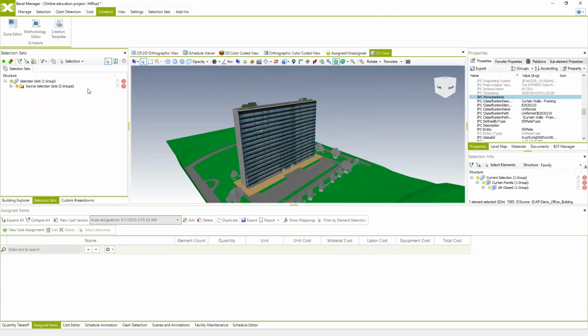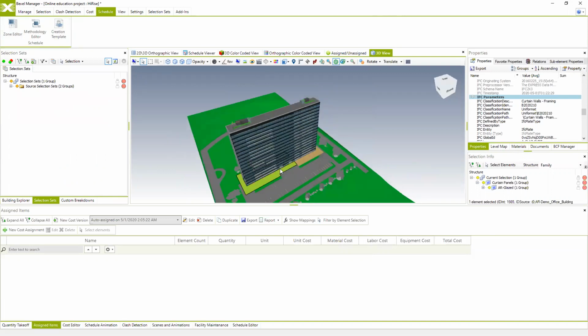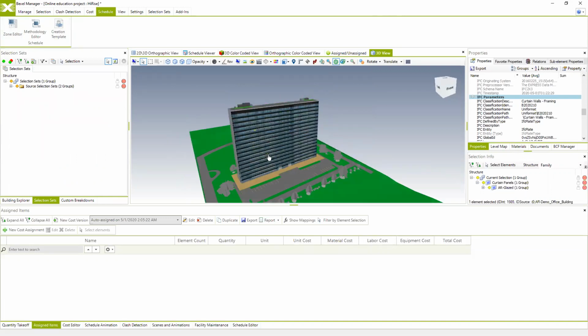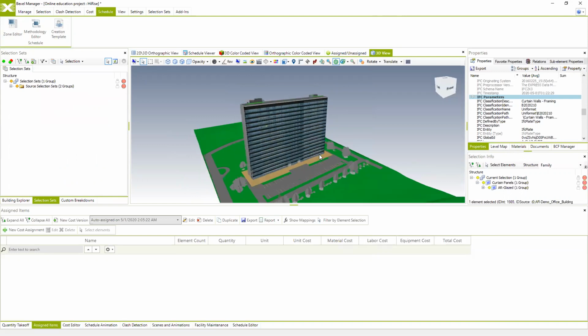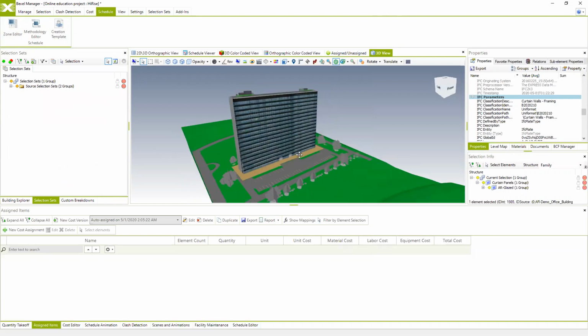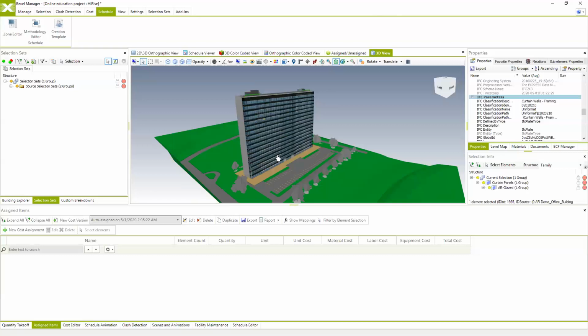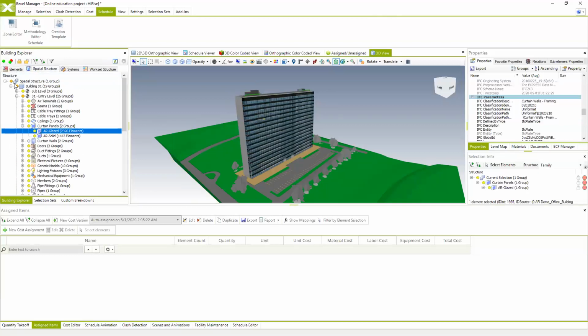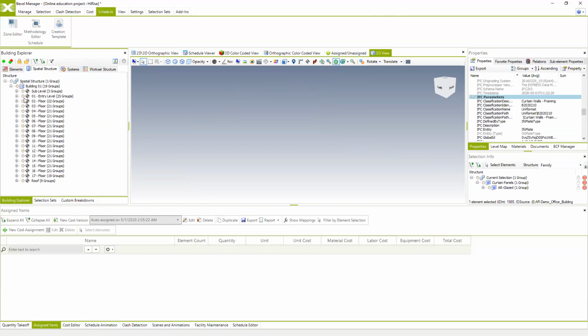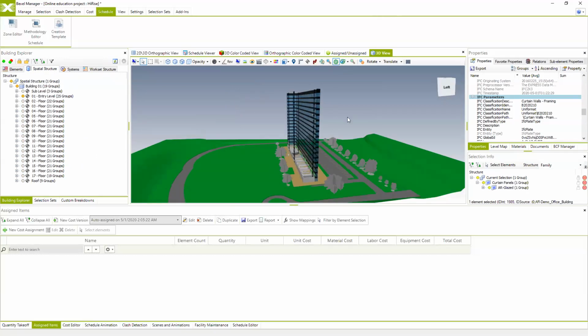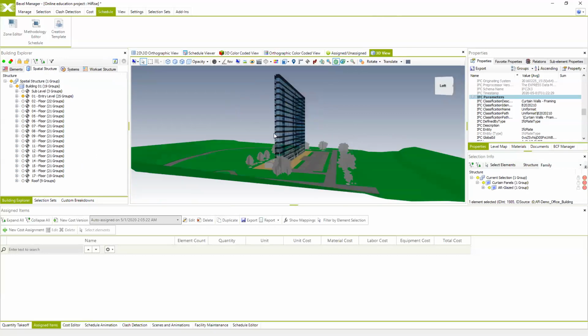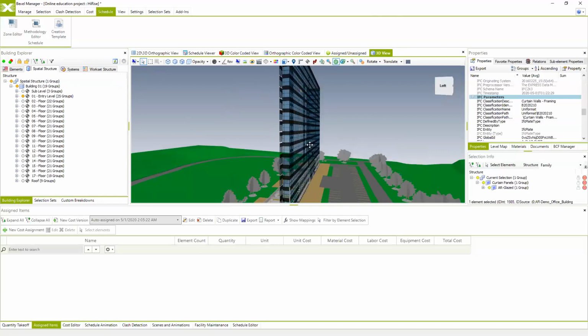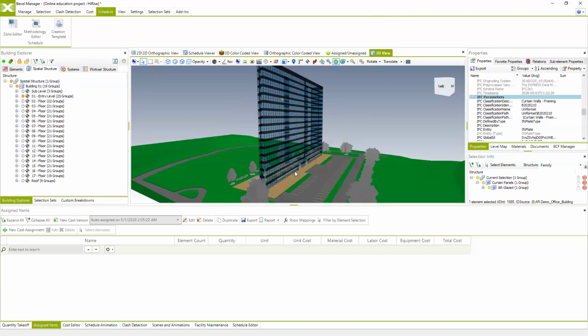And also something which is a really common error when it comes to IFC files or exporting files from Revit into IFC is that the segregation of these elements according to the levels of the building is not always perfect. For example, I know that the facade as curtain wall is always related to the base level.